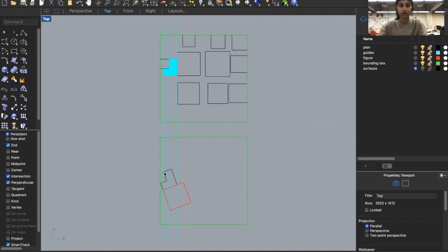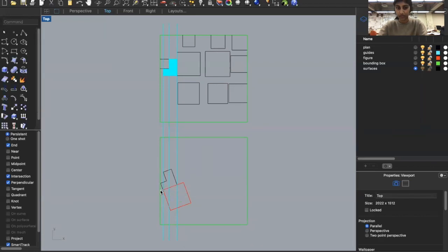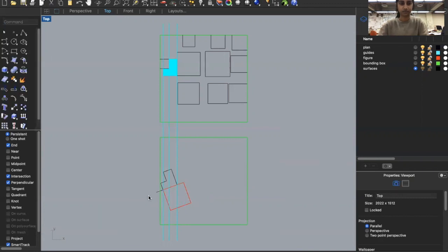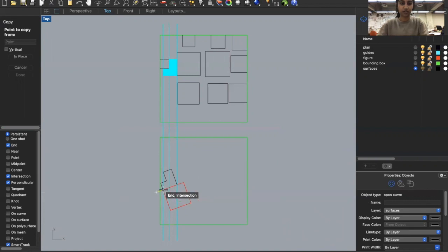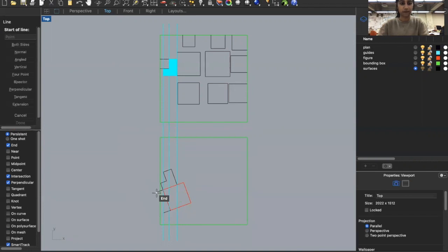So now that we have one face, we can go ahead and continue unrolling the other faces. So I'm gonna start doing this side right here, and that would be this side right here. Since I know what this distance is from this point to this point, we know it's 21/32. If I want these 2 corners to fold up and line up, they're gonna be the same. So I'm gonna draw another line that's perpendicular to my square, that's 21/32 inches in this direction. And then I'm gonna copy that over for the entire length of my figure and connect the lines.